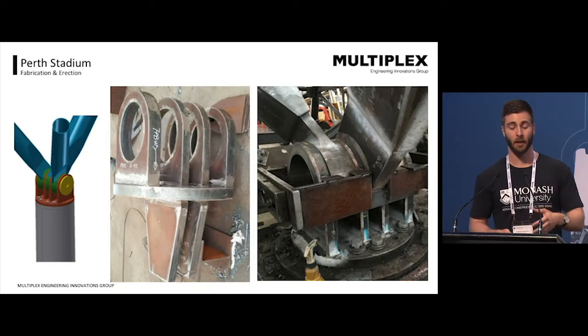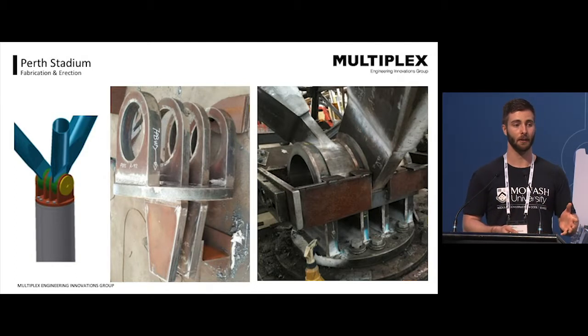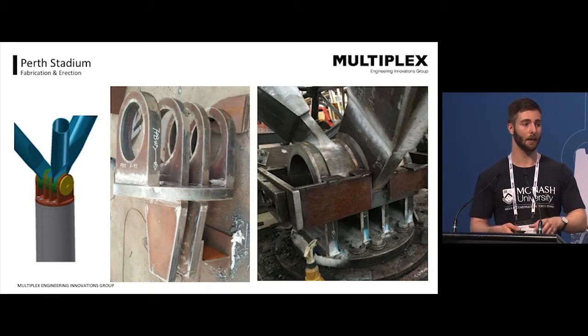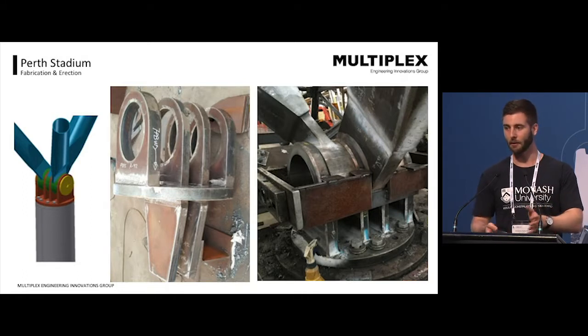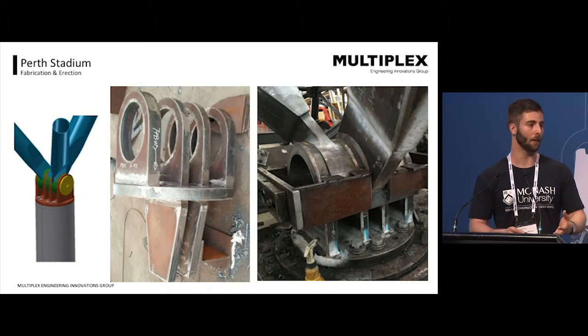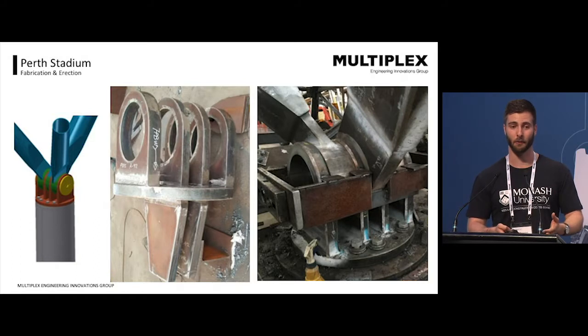So an important aspect for this, like I was saying, is that a lot of it can be prefabricated off-site. So here we've got the fork plate and the connections being tested for fit, and a lot of this work is able to be completed by the steel fabricator, which we had a lot of input from as to how we could make it easier for them to construct, both in terms of fabrication and when it does actually get installed on site. So again, we think that's quite an important aspect of our designs, taking input from another perspective, from the guys who are actually going to be building this in the final instance.